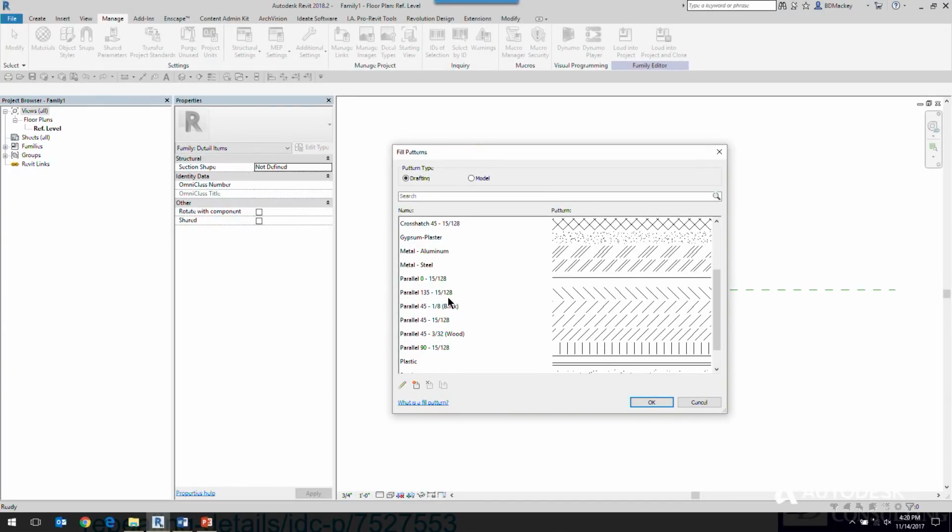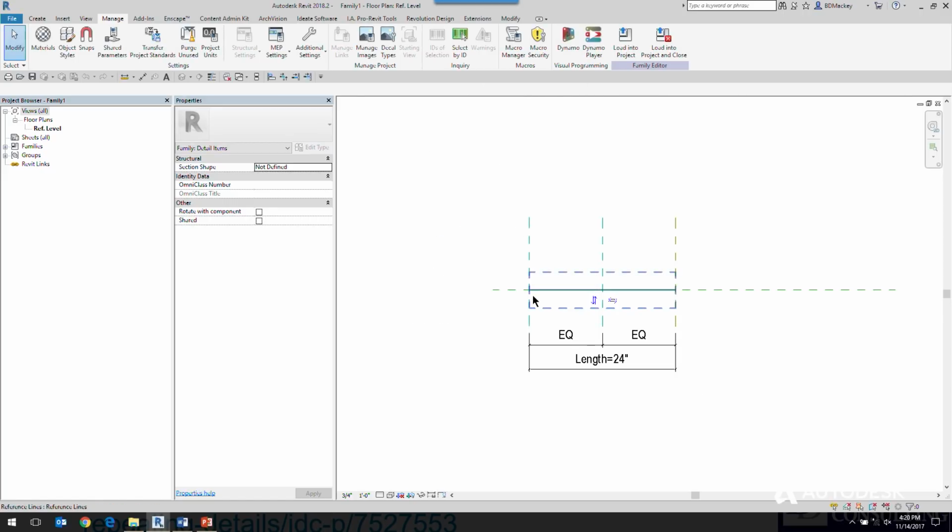So for me, getting all of this set up in your family template becomes very, very beneficial. So when anybody in my office needs a new template or a new family, they go File, New Family, it's pointing them to where our custom templates are on the server, and they don't know any different, but it's got all of the stuff that matches our standards. And by the way, when you do this, don't spell something wrong and then load it into 15 families. It's a pain in the butt. Okay, so have this stuff all set up as you get started. Possibly have things built inside of there too.